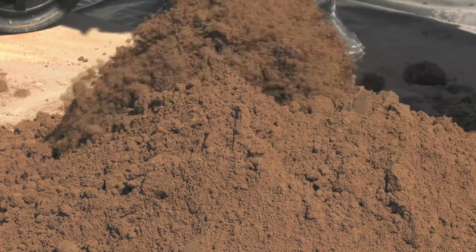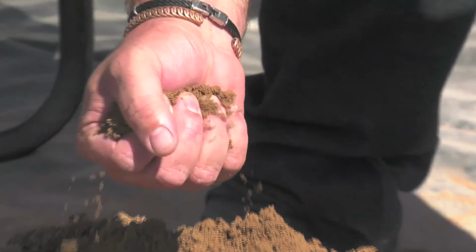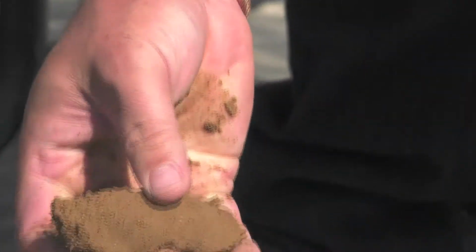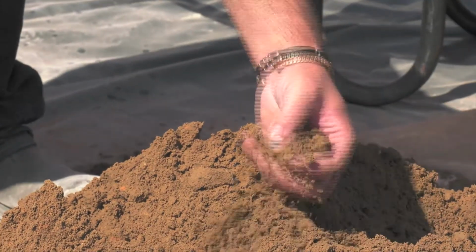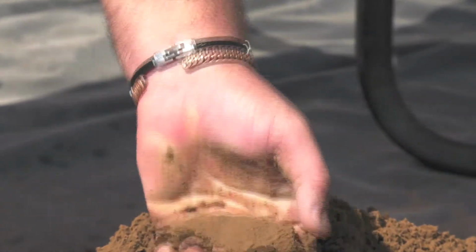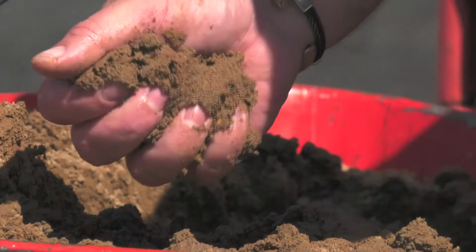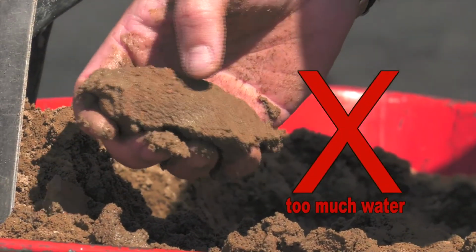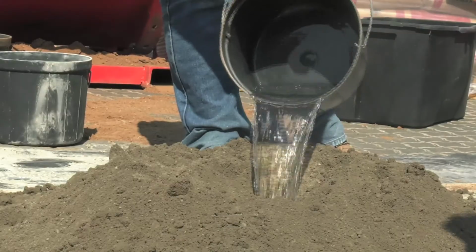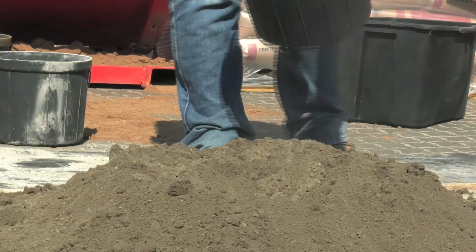In order to determine if you need to add additional water, take a handful of the mortar mixture in your hand, squeeze it and release. If it breaks in your hand, you need to add additional water. If it remains compacted in your hand, the mixture is good. If it remains compacted but you have a smudgy, wet surface, you have too much water in the mix. Always add water in small amounts at a time to prevent adding too much.